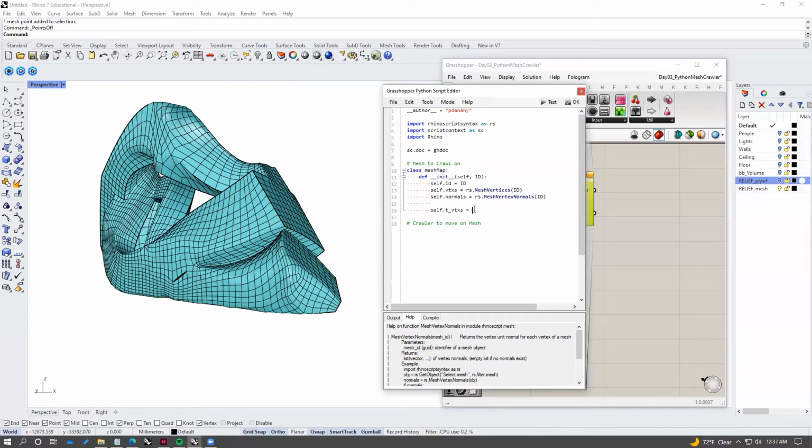So there's documentation online for this, but you can actually visualize what we're looking at by typing rhino.geometry.mesh. So this is accessing a mesh class, and then if we type another dot, we can access methods within that class. So one of these methods is actually to extract the topology vertex list. So if we just type topology vertices, this will give us the topology vertex list.